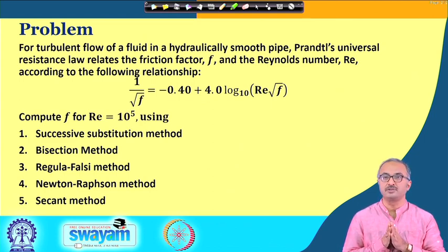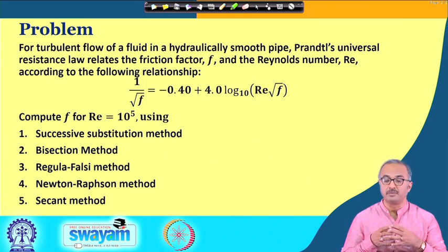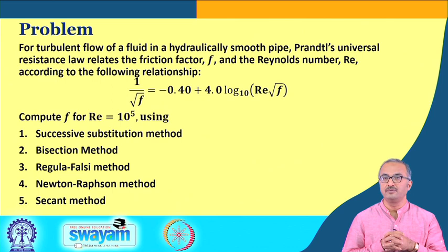So, this problem pertains to the evaluation of the friction factor, to know how much resistance a fluid would encounter when it is flowing over a surface or in a conduit. How does this knowledge help us? It is required whenever we are designing a system in which we push the fluid using a compressor or a pump. Depending on the friction factor, the resistance to the fluid flow will change, and then we can understand how much power is required for a pump or compressor. So, for all these reasons, we often need to evaluate the friction factor.